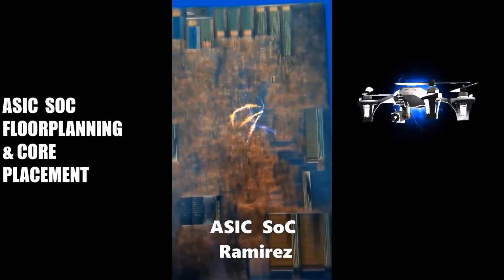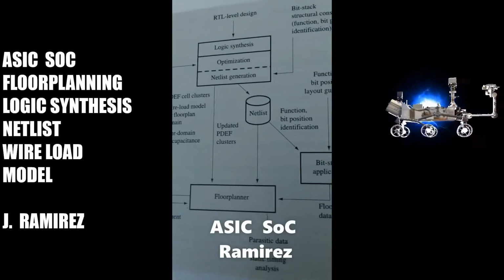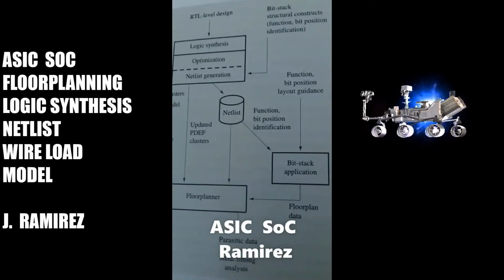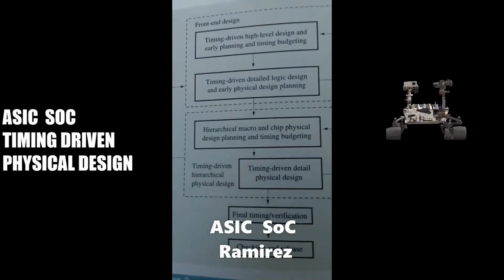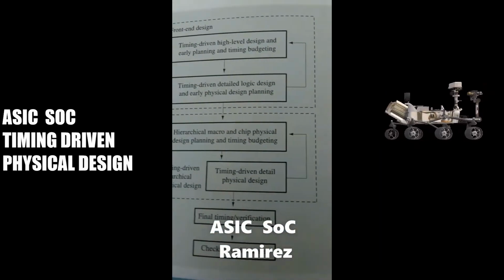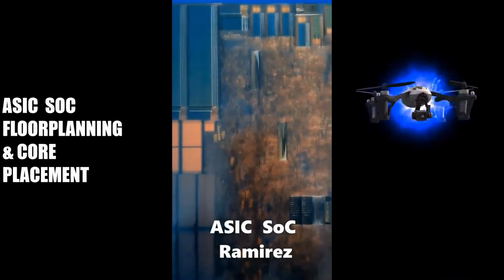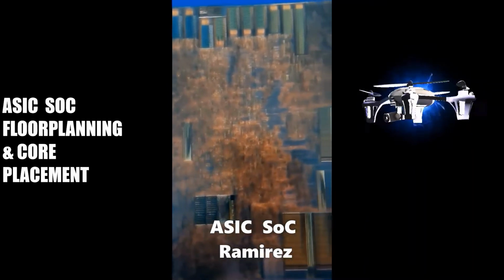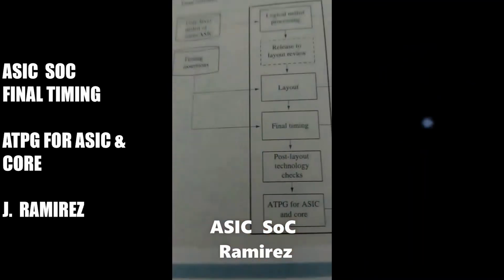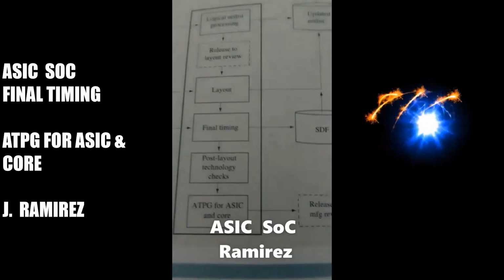The design of a bit stack uses a general methodology. First, data flow logic is logically separated from control logic. Then each data flow bit position, typically spanning numerous data flow functions, is isolated, and the circuits are placed along the same circuit row, minimizing the amount of wire required for the buses.